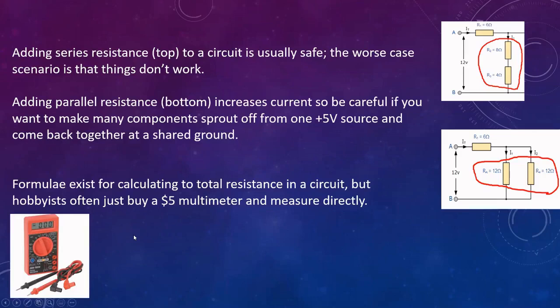It's also good because sometimes resistors, if you use them a lot, you can break their leads. They're very, very finicky little wires, and if you push them in and out of the breadboard enough times, they can start to break.